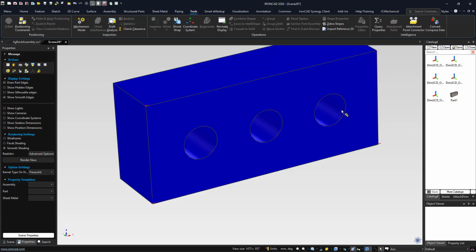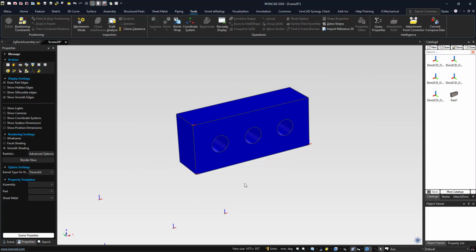The nice thing about these attachment points is if you have patterns. So if you have a pattern, then another one comes in or removes, your Smart Annotations will update. That's one thing the Auto Dimension tool cannot do because it has to recreate it from scratch, and it just does what's visible at the time. This one will allow you to add and remove pattern elements, so it's a very powerful tool in that nature.